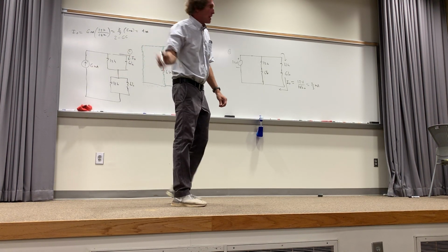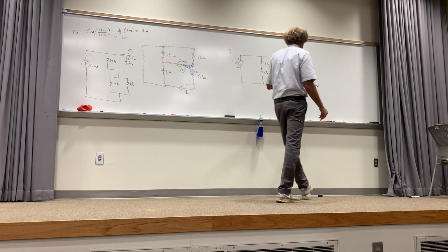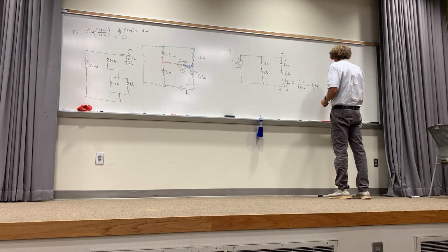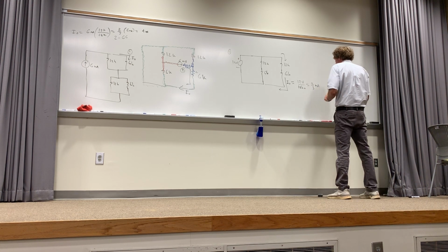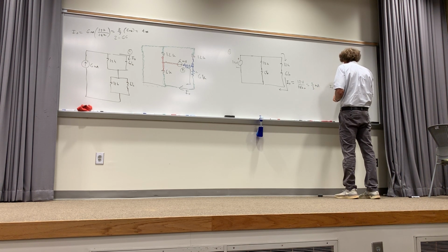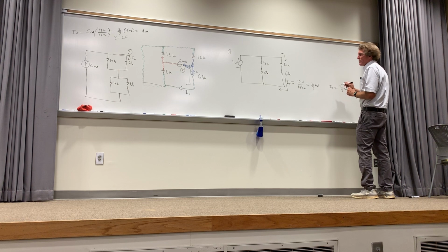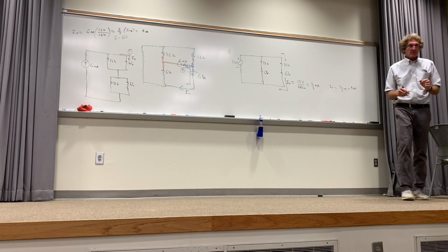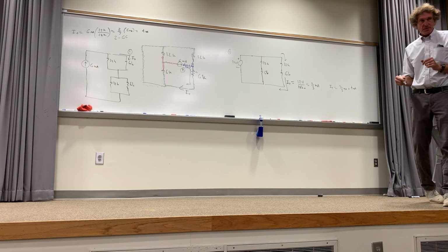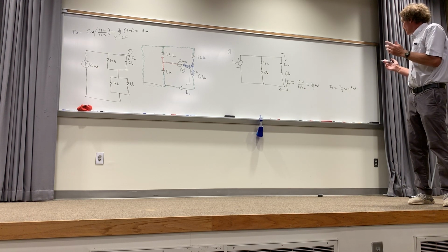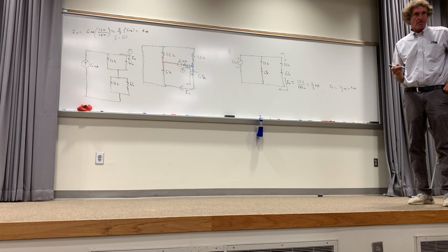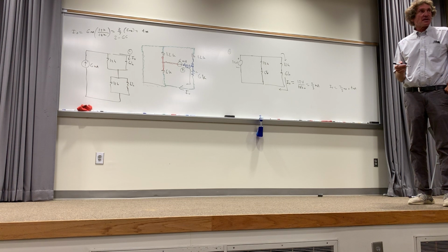Everybody? That means the total current, this superposition of this plus this, I total would be equal to 2/3 of a milliamp plus 4 milliamps. And is that the answer? It is posted. Okay? There might be 4.666 milliamps or some formula. Is that it? All right, you all see what I've done there?